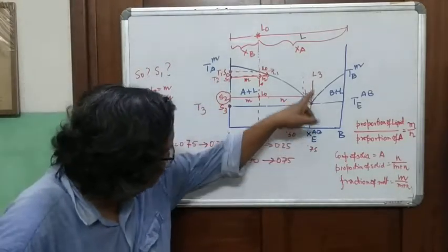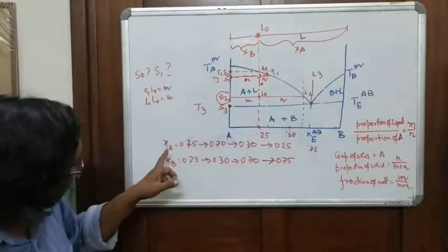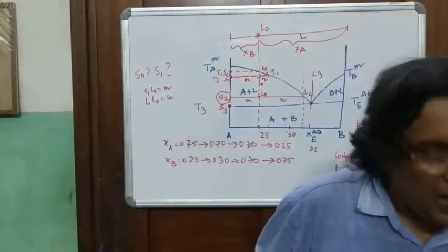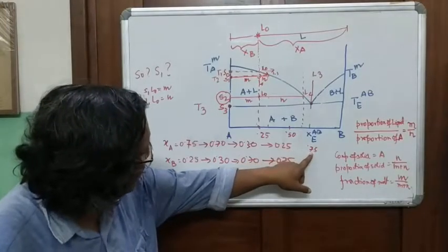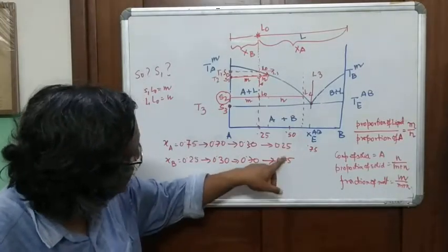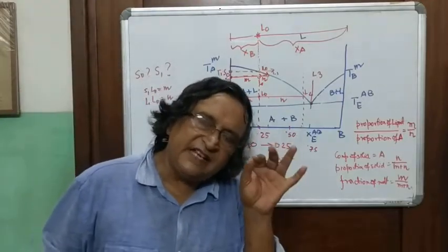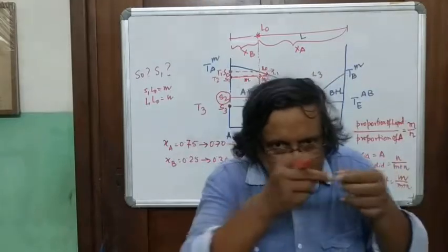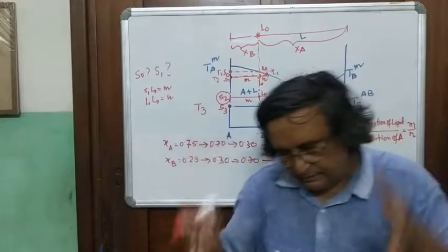By the time the liquid composition reaches the eutectic, A and B components in the liquid are in the proportion 0.75B and XA is 0.25. That is the composition or proportion of A and B in the chemically homogeneous melt.